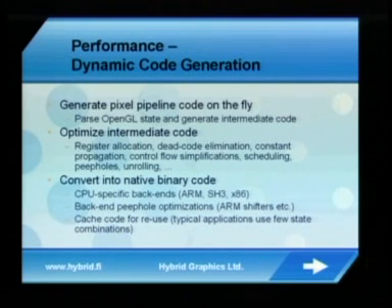Perhaps the most challenging area for us was the pixel pipeline. I guess many of you already know that it consists of a number of states, and if implemented in a really naive way, you would have to do maybe 20 or 30 or even more switch cases to see which depth test mode you are using and which texture combine mode you are using. Are you using bilinear or just point sampling? All sorts of states. And it's pretty hard to deal with that in a well-performing way.